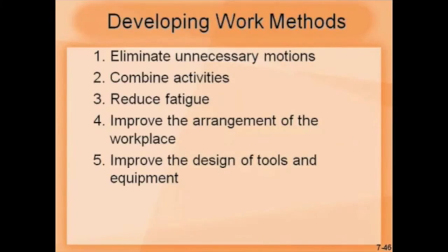Now coming to developing work methods. After using those techniques, one gets an idea what are the non-value adding activities. So the first step, or the first item given here, is to eliminate unnecessary motion. If possible, combine activities. Then reduce fatigue, because that can have a big impact on productivity. Improve the arrangement of workplace.